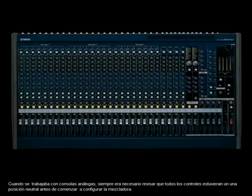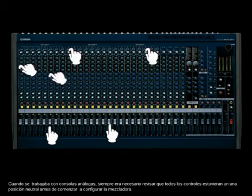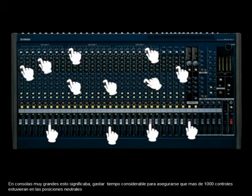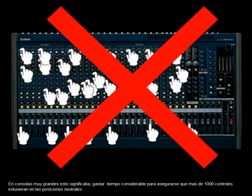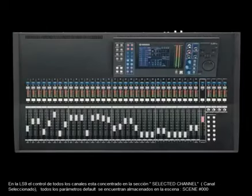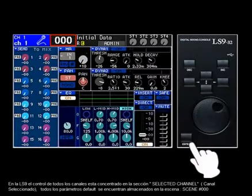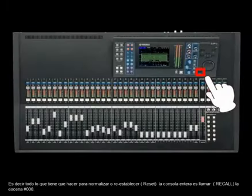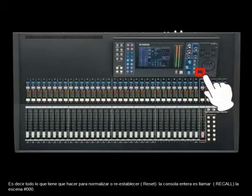When working with an analog console, it was always necessary to check that all controls were normalized before setting up a mix. On most large consoles, this meant spending a considerable amount of time making sure that more than 1,000 controls were set to the appropriate neutral positions. On the LS9, all channel controls are concentrated in the Selected Channel section, and all default settings are stored in scene number 000. So all you have to do to normalize or reset the entire console is to recall scene 000.